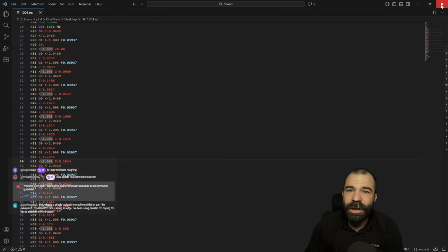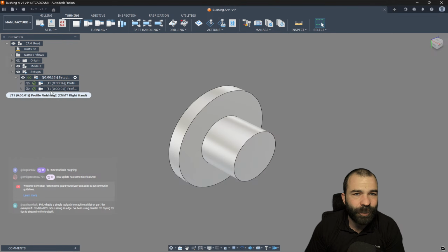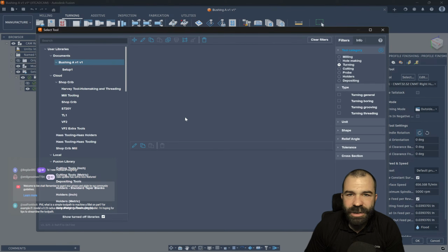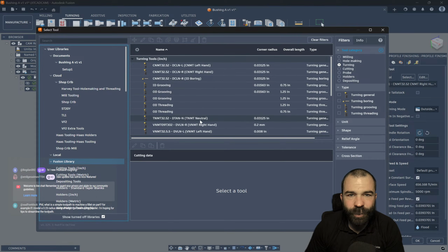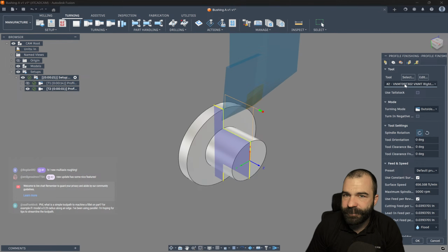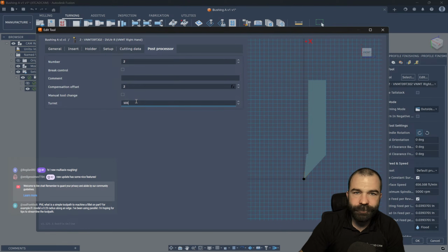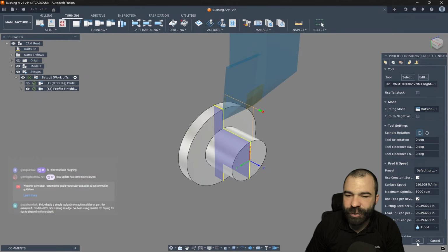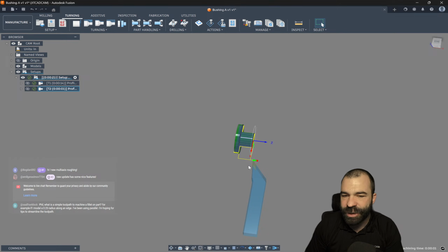So again, we're going to go back and do a few more things because there was one more request from that customer. We're going to swap out, so I'm going to take out tool 1, and we are going to do this with a different tool. Let's say we're going in with a VNMT right-handed tool, and again, I'm going to set that tool to turret 101. So again, this is very important that you're utilizing a turret number if your tools are coming from the front side of your machine. Now, if you guys are wondering, in the world of Fusion, yes, my X would be pointed away from me. I'm just doing this as a visual representation that you're feeding in from the front.